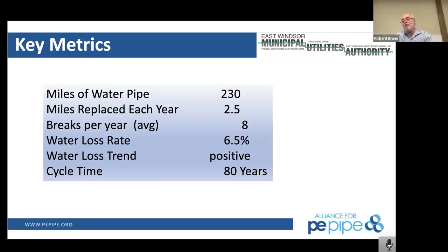Okay. On our condition assessment on the pipe, we have cut pieces of pipe out of the system and had it tested. That was about 10, 12 years ago we did that. But a lot of our assessment has been by our crews out in the field. We get a water main break, they're out there. I would say a good 70% of our breaks right now are circular breaks, and that's due to the freeze thaw of the environment, the climate that we're in,